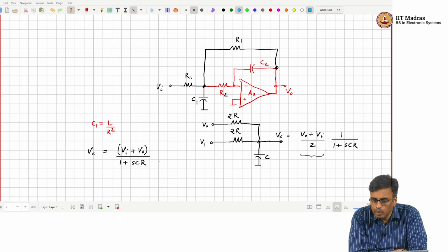What comment can you make about stray capacitance? Look carefully, even without the effect of stability. Across C1, if there is stray capacitance, it will change the transfer function. But at the other two nodes, it is fine, and that is the price you pay.